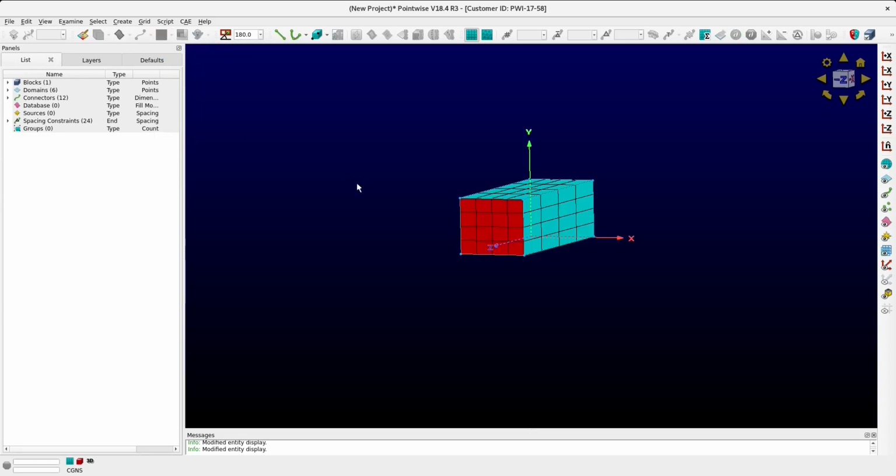Right now I have to be careful not to select other grid elements when I'm working with the surfaces. Although for this example, it's not very problematic, it can become a major issue for larger geometries. So to avoid this, Pointwise provides the masking tool where I can deselect volumes and lines, and this will allow me to work exclusively with the surfaces.